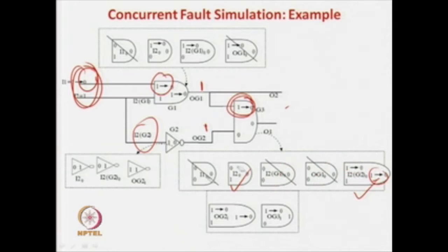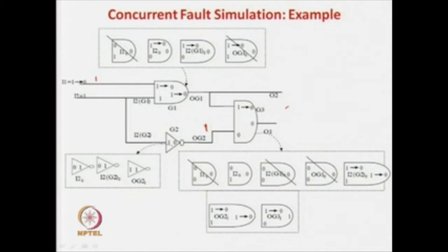So this is retained. Now similarly you can easily verify which other gates are retained. O2 G1 stuck at 0, this one if you are going to get a stuck at 1, then this one will be changed and then the output will be changed, this one will be a 1, but there is a signal difference with this normal gate, so this is retained. And O G3, the output G3, if you just think of this case, this fault is also going to be retained because this is the stuck at 1, okay, and this is the signal change only because of this signal change.